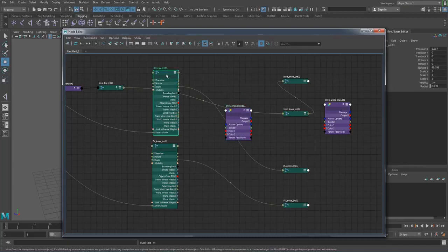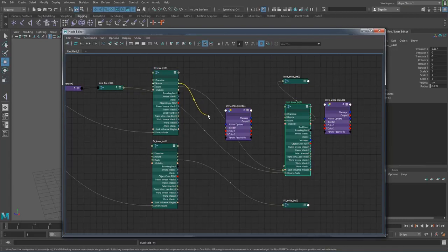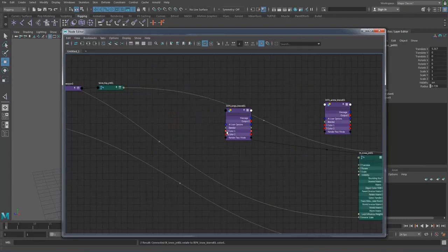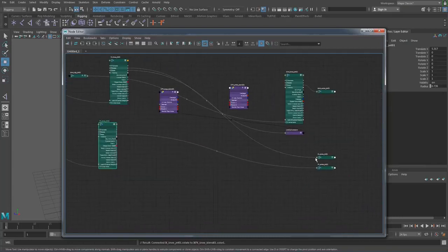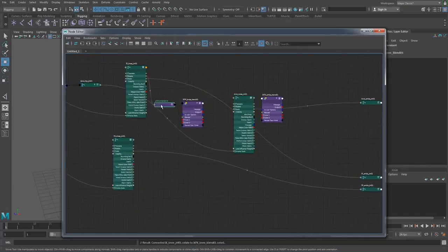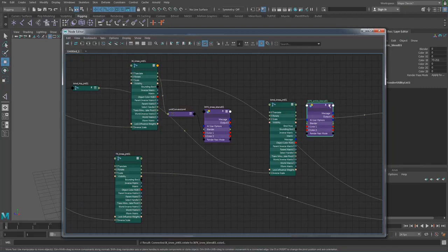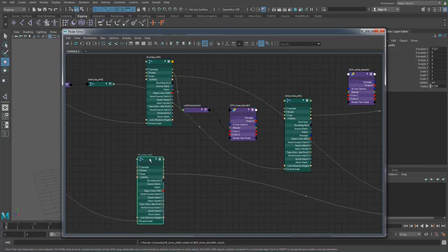So again, pin these, and actually I'm just going to show you what happens if you don't pin them, because then you can understand the pain of not pinning them. If you was to click rotate and nothing else is pinned apart from that, if I go to color, that happens, and it, again, is frustrating. There's no kind of reason why they should do that, but they do. So do just make sure you're pinning them, otherwise they do just jump around, and it becomes very difficult to put them back to a way in which they actually make sense. There we go. Sorry. So just pushing P there for pin to actually have it so that these don't jump around like crazies.